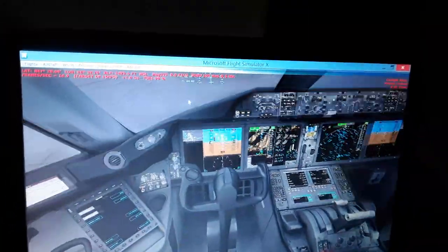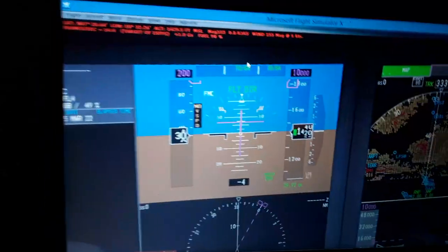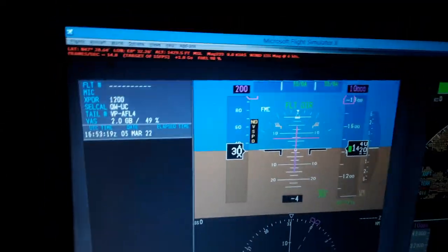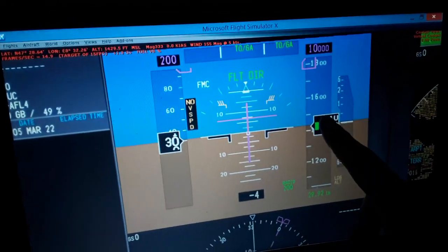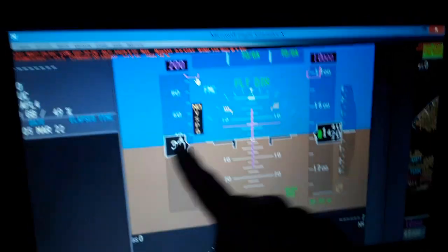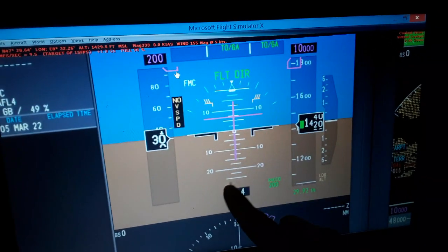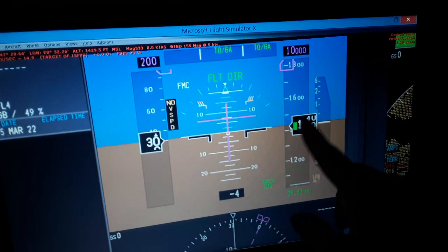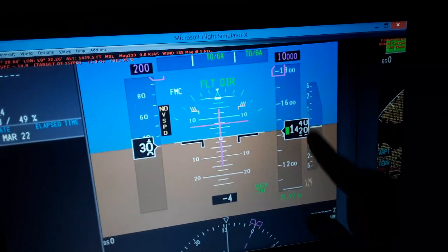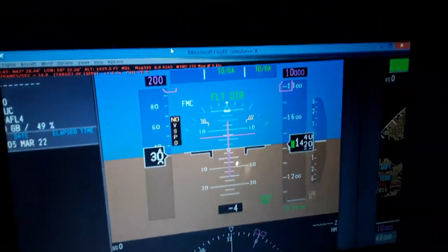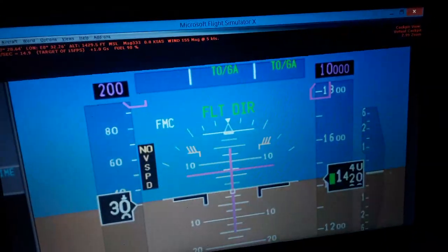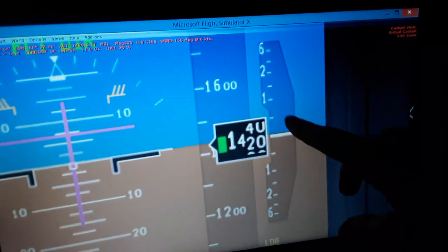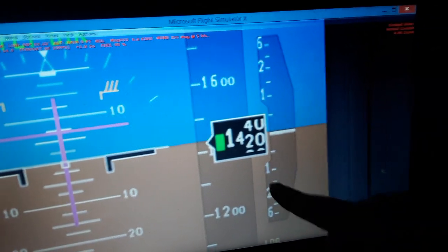You can see here. So we have the primary flight display over here. Very important, the airspeed tape. You can see the airspeed indicated, the airspeed selected from the autopilot flight director system panel, the barometric altitude. So this airspeed and altitude, altitude above the ground, altitude above the sea, barometric altitude, the vertical rate of climb and descent of the aircraft in tens, hundreds, thousand feet per minute. You can see how fast the aircraft, the rate of climb or rate of descent, vertical speed indicator. So this needle moves up when you climb after takeoff, or moves down when you descend.